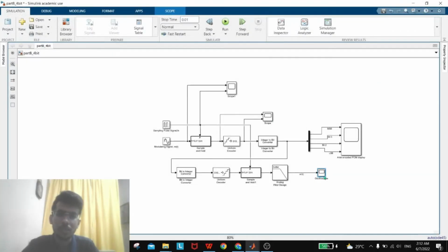Last but not least, if we compare parts A, B, and C, we can notice that part B, which is done by multimedia, can produce a stronger signal compared to the others. This is because part B consists of a bigger step size for each quantization level. As we know, the bigger the step size, the less the quantization noise. Okay, that's all from me.